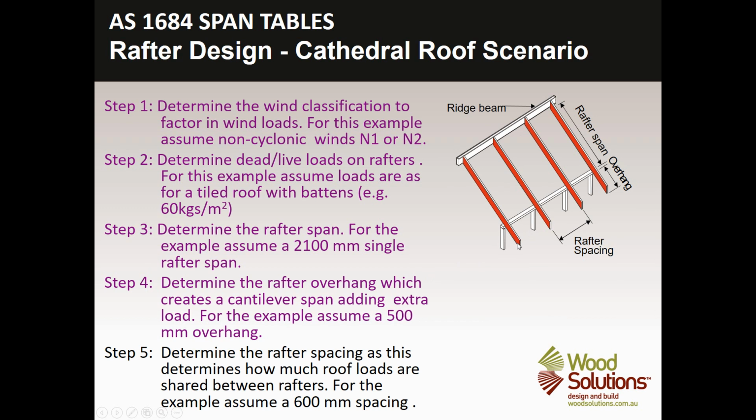So that might be our killer. We'll see that when we get to the span table. Determine the rafter spacing, as this determines how much roof loads are shared between rafters. For example, assume a 600mm spacing. So our rafter spacing is 600mm.